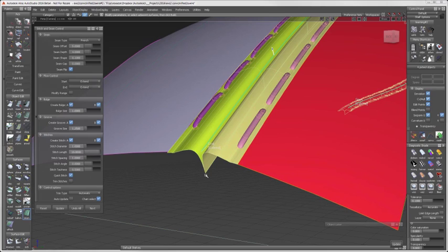While experimenting with stitches, turn Quick Stitch on and trim stitches off. This will speed up your operations. And then once you've determined all the parameters, reverse the order of these switches to create the final surfaces. The Stitches control panel is added and gives us control over the stitch parameters.